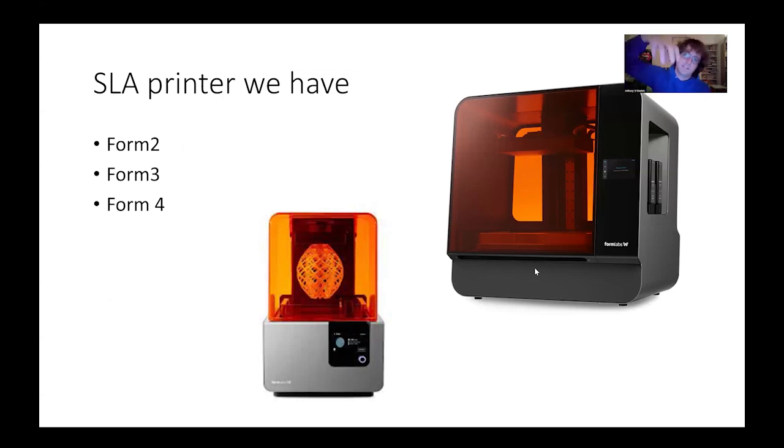As you can see, the print is held upside down and dropped into the vat, and then pulled up through the liquid, and each layer is formed. So pretty cool. It has scaffolding supports that hold it on from above. Basically, as you can see, the part in this Form 2 print here lowers down onto the vat that's underneath. That's where the liquid resin is dispensed. The screen is underneath the orange hood here. That's where all the moving components for all the optical stuff and the power that cures your part are.